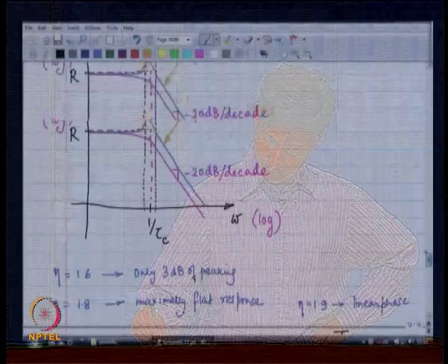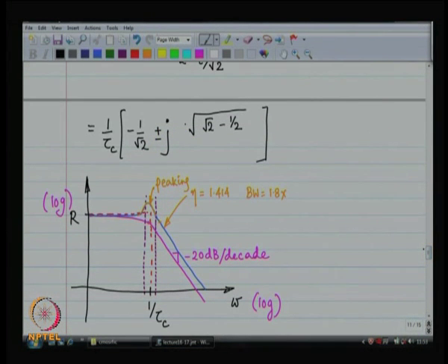I am going to discuss one more, which is using the principle of feedback. So far what have we seen? We have seen that instead of having a regular RC circuit, we can introduce some poles and zeros, a pair of complex conjugate poles and a zero, right, and we can try improving the bandwidth.